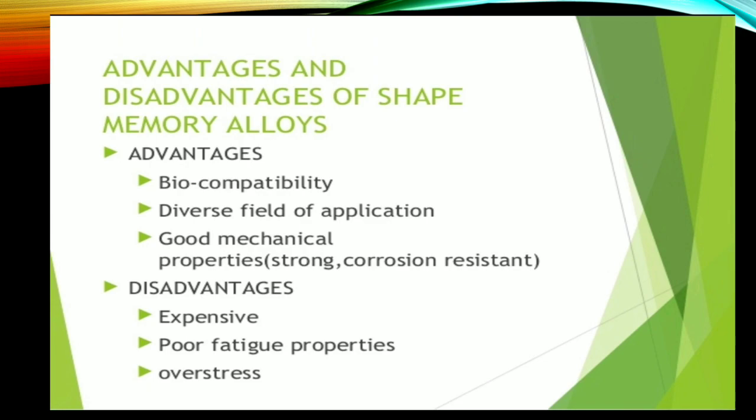The other reason why the popularity of polymers is high is the low processing temperature. Hardly 120, 150 or 160 degrees Celsius is required. When you want to store water or brush teeth, generally we are working at room temperature. At that kind of temperature, they can be very easily used. It's not a problem. The problem with non-metals, generally polymers, comes only when we use them under high temperature. We will discuss what difficulties we face in non-metals and how they are overcome in composite materials in the next class.